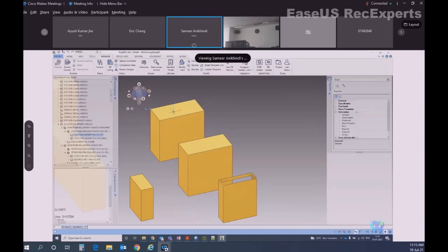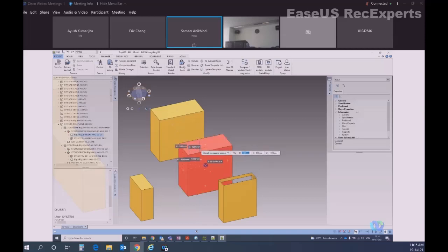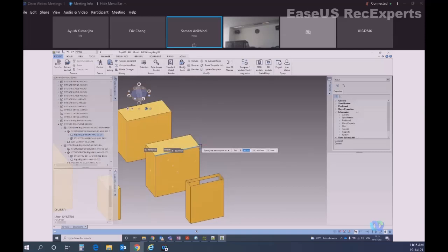So for example, I am using the distance command. In the ID command, you will not be able to see this. Use the distance command. I will snap this corner, so it will always be absolute. I cannot make it relative here. This is the first point. Click here. Now automatically the second point becomes relative to the first point. You can see this distance of 2002 meter and northing -1 meter.